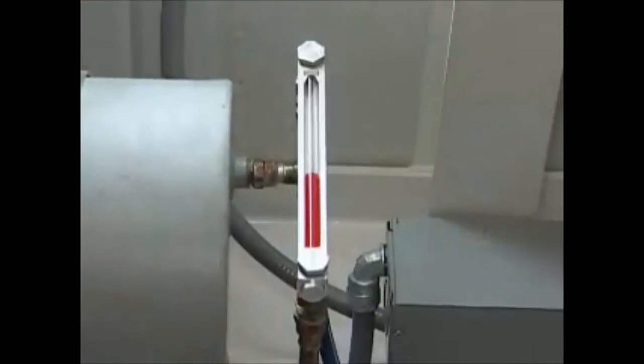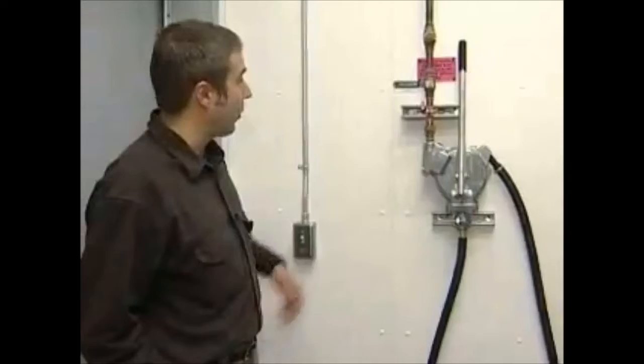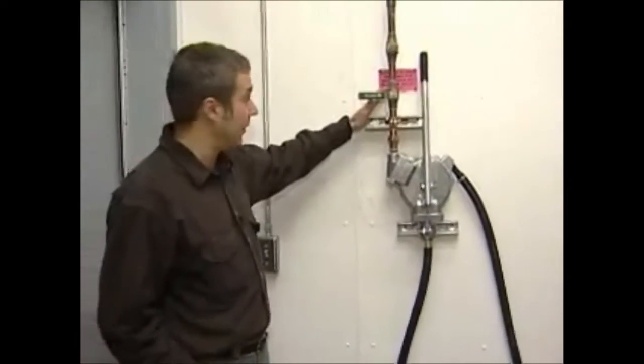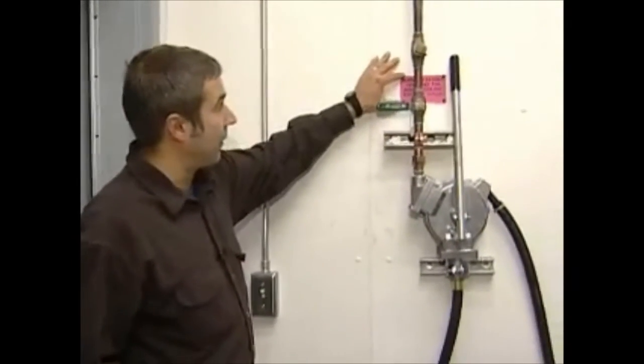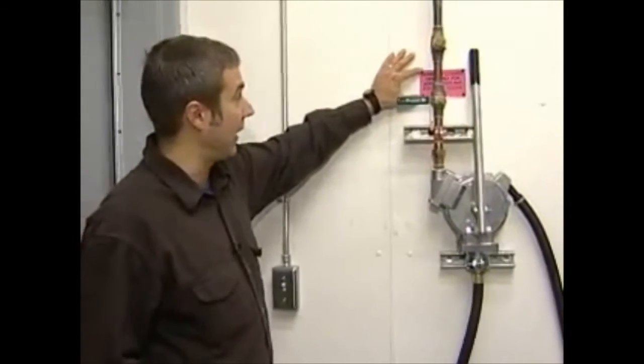So you can look at the sight gauge. That's part of the daily check. Make sure you're up about 2/3. If you get a little low, there's a point here for adding glycol. Now I want to make note here, this valve is tagged normally closed, open only for adding coolant, ethylene glycol only.